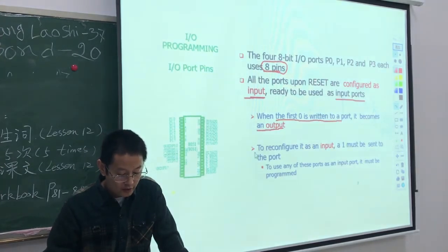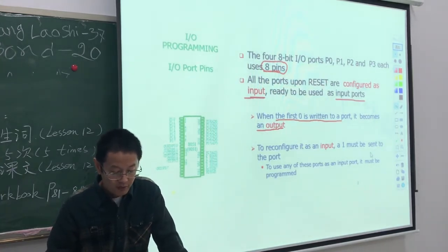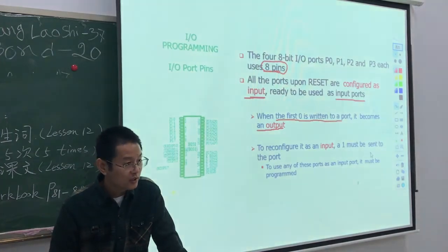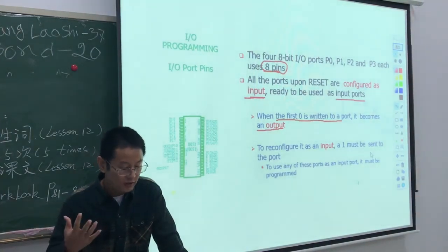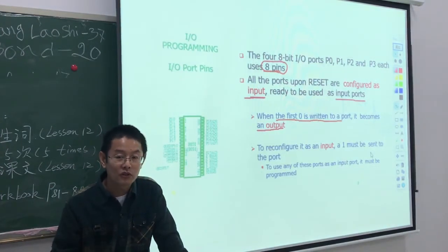You need to remember this. To reconfigure it as an input, 1 must be written to the port, which means before you use the port as an input, you need to write one to the port.